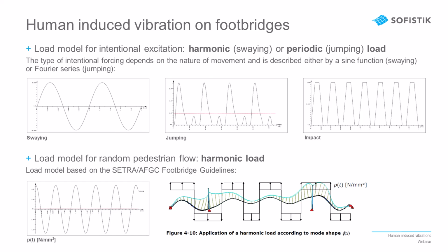A repetitive impact, or any other scenario for that matter, can also be introduced into the model as a discrete polygonal function that can be defined by hand, by spreadsheets, or by using parametrics. Several data pairs are required, with each pair describing the numerical value at the specific time point. SOFiSTiK is able to interpolate linearly between those time points to create any loading function.